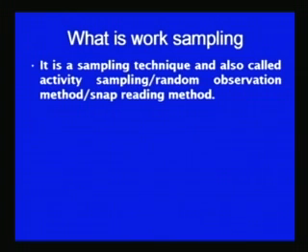The work sampling is significantly different, because in this technique work is measured by having random observation of the shop floor or work area, to find out how the work is being carried out, where workers are working or machines are being run, and where ineffective time is present due to the idleness of machines or workers. The reasons for the ineffective time of either machine or workers can be obtained through the work sampling technique by quantifying the reasons for ineffective time during the operation.